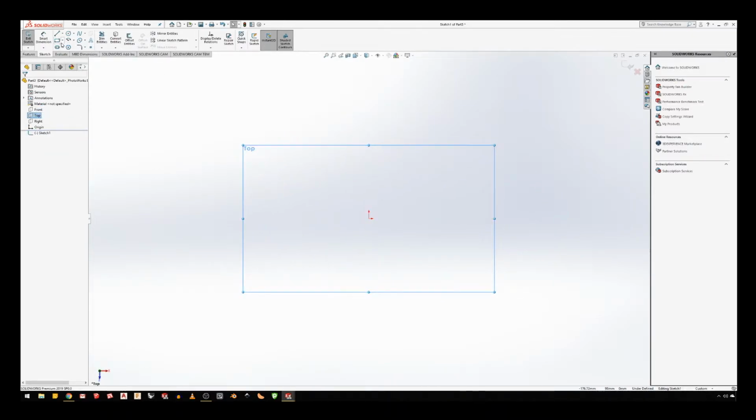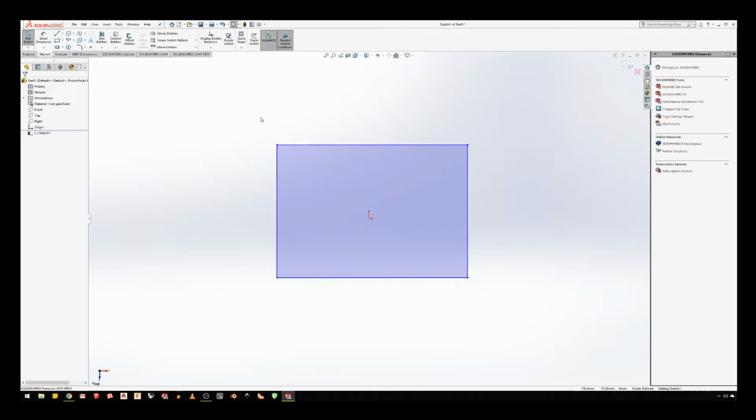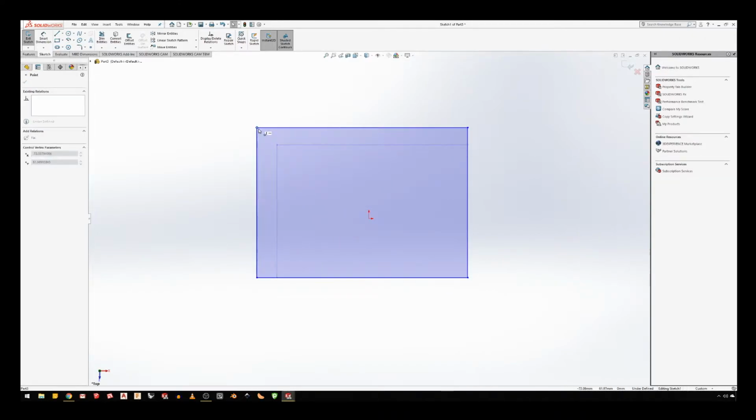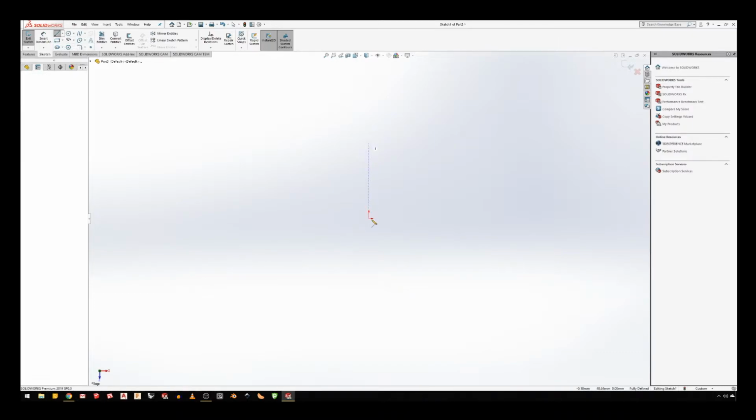And let's look at the rectangle tool, which is just below the line tool. So our first basic rectangle tool allows us to draw from corner to corner. This is not very constrained, as you can see, and it takes some time to constrain it to things. Like I had suggested in the past, using the center line tool and drawing a small L shape helps a lot in constraining objects later on.